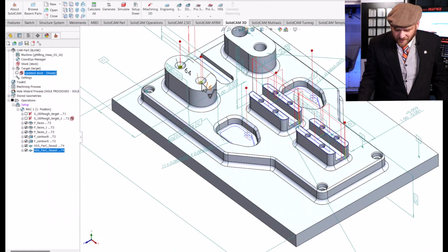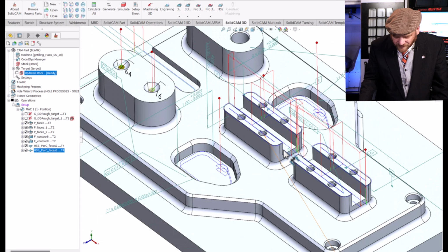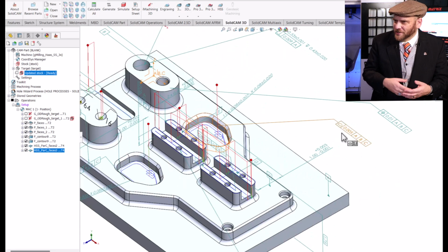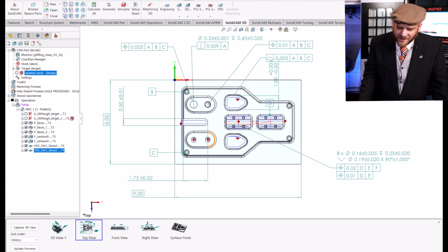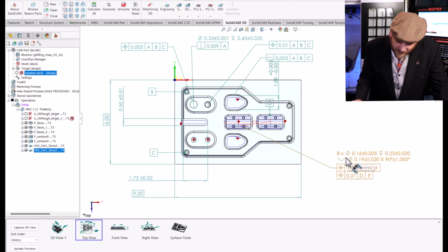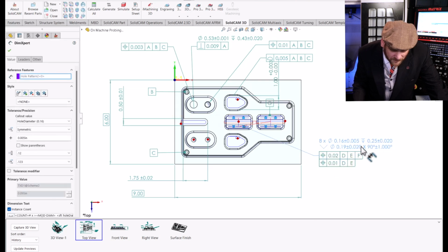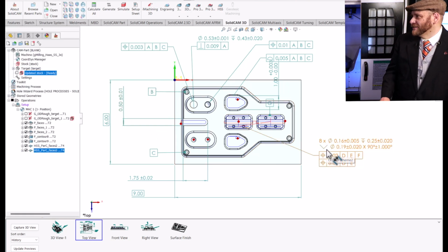I have these chamfers called out. They're all pretty open tolerances. They're all plus minus 10, plus minus 20. They are plus minus, so I can make them right to the mean. But their diameters are called out. So you can see here in my top view where some of these counterbores are called out. So it's plus minus 20, and it's a 190 diameter. And I'm going to trust this data over anything in the solid.